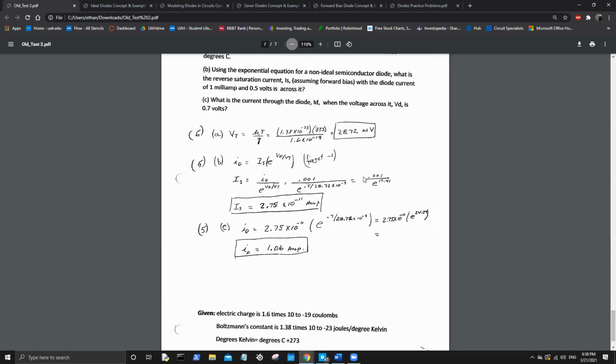Because look what happens with that E value. E is no longer in the denominator. It is now part of the numerator. E to any large positive number is ridiculous. So you need to have a comparatively small IS to make your current across your diode remotely acceptable in real world terms. Mathematically, that's a good way to think of it.